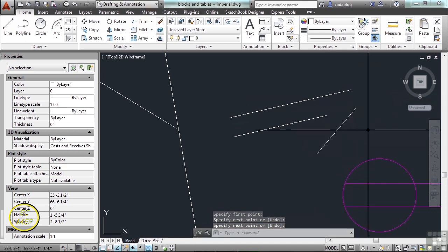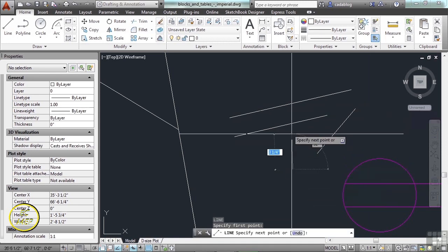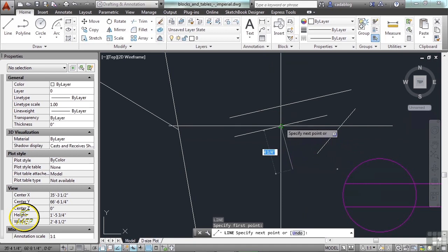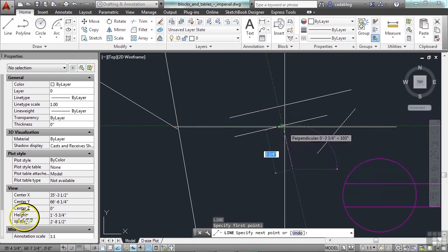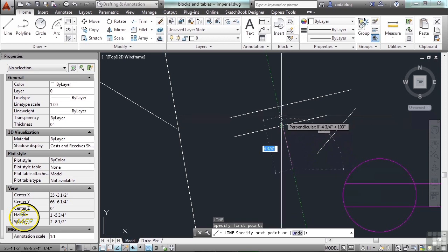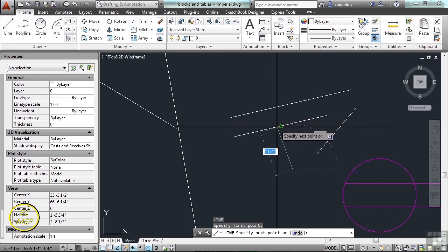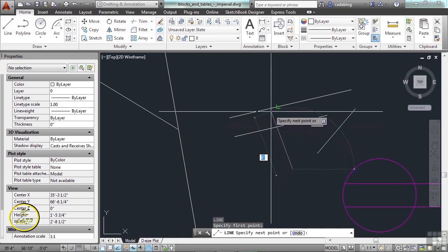And again, it can be tricky to use. You have to follow something exactly. You have to follow the path. You can't really be shaky as you go about. You can see that things are going to move and it's going to pick up other trackable points. But I can do that with any snap point. Here's a perpendicular line. I can move it and see it's tracking up, or even perpendicular, or this intersection point. I can do a lot of different things.